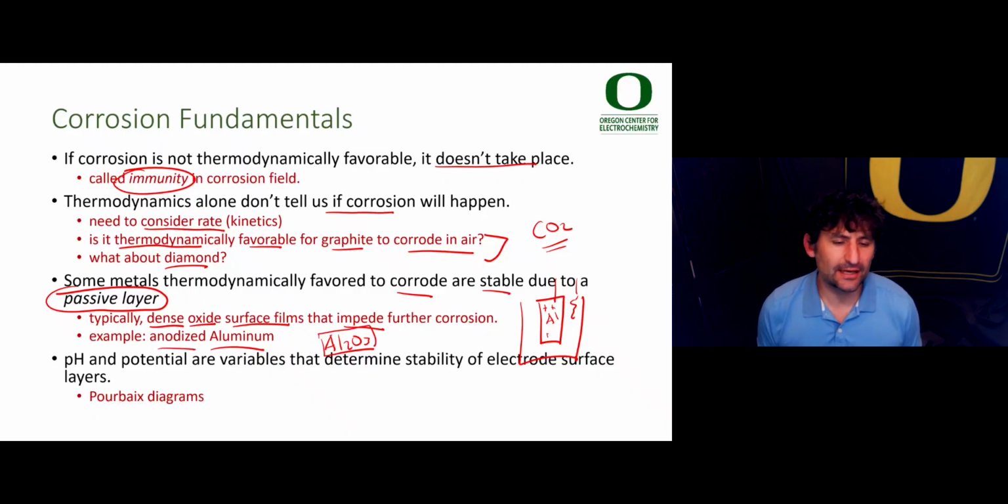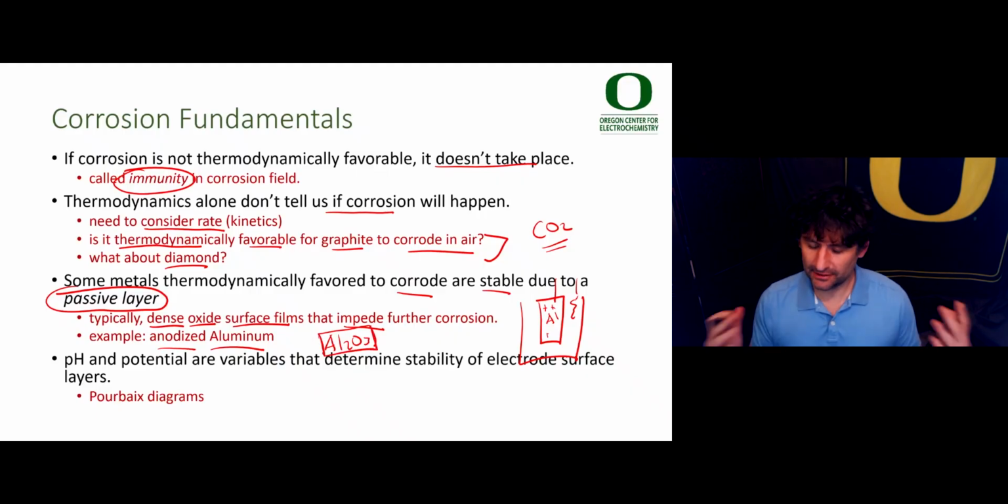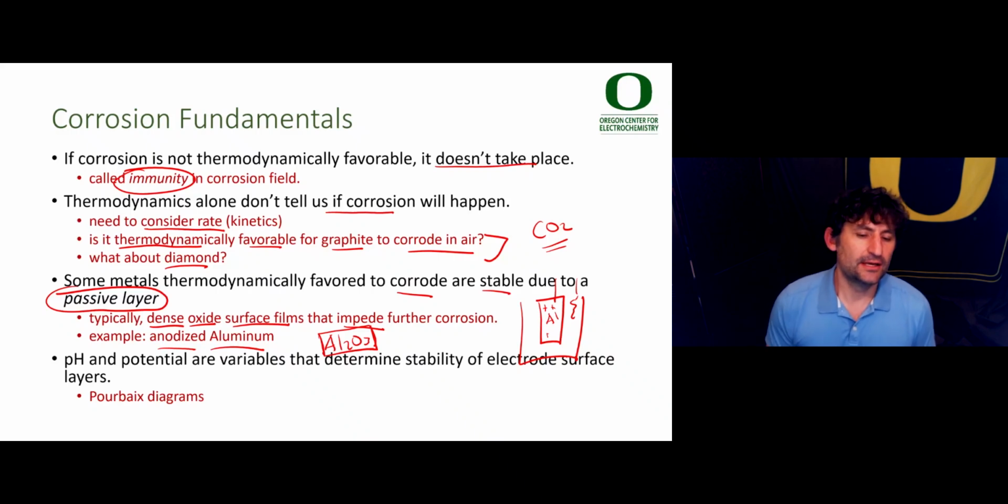You've had anodized aluminum all over the place. Your laptop, your bike, things like that often have anodized aluminum pieces. And you do that so you get a nice, thick, dense layer of aluminum oxide that prevents any other corrosion from happening under natural conditions in exposure to air and rain and water from rain. And that allows you to maintain a nice finish on aluminum metal.